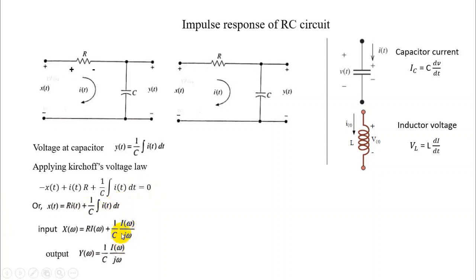As in differentiation we discussed that taking the Fourier transform of any differential part just needs multiplication with j omega, where X(omega) is the Fourier transform of x(t), similarly, to take the Fourier transform of any integral part, we just need to divide by j omega. This is the procedure.